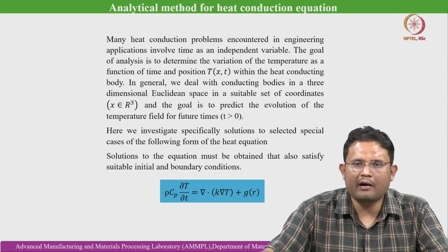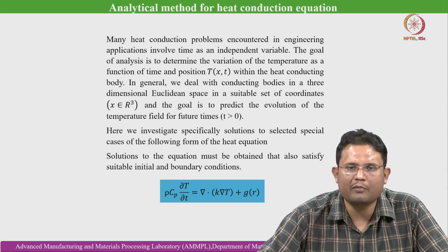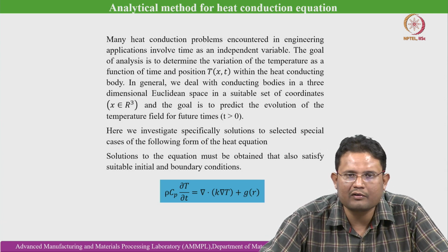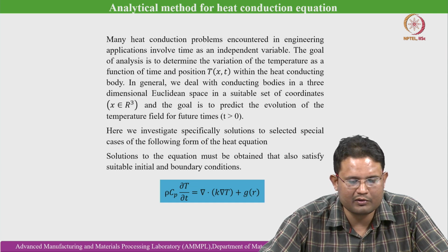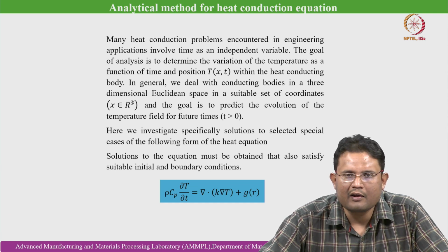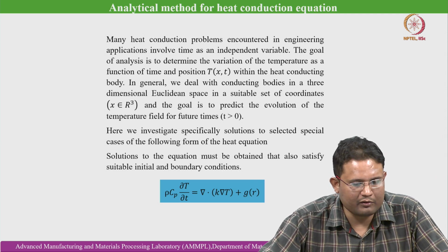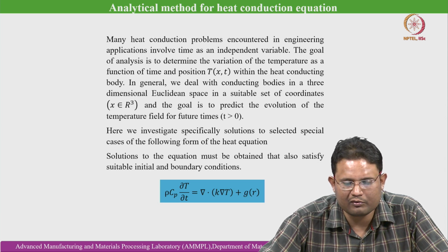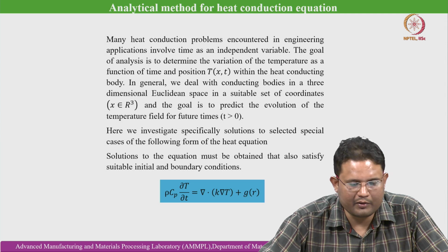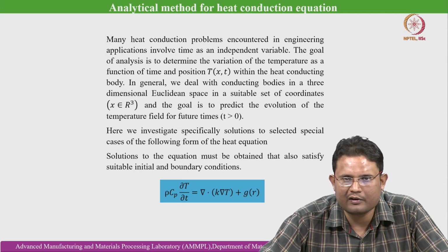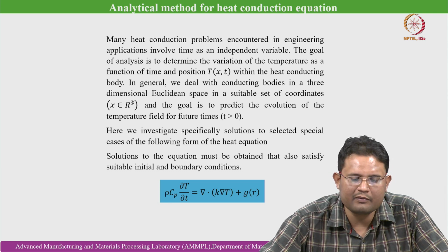Okay. As we know, many heat conduction problems encountered in engineering applications involve time as an independent variable. So the goal of the analysis is to determine the variation of the temperature with respect to space and time within the heat conducting body. In general we deal with conducting bodies in a 3D Euclidean space in a suitable set of coordinates, for example x, y, z and or r, theta, z. And the goal is to predict the evolution of the temperature field for future time steps, that is t